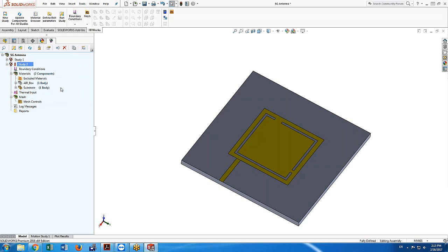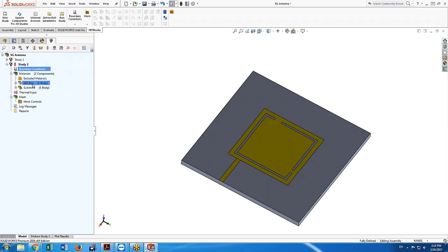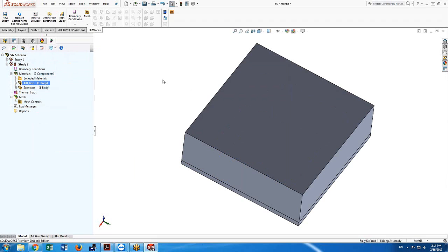That's how the feature geometry looks. So you get the boundary conditions, and the boundary conditions are really straightforward for antenna. Port is port. In this case, let me go ahead and show the air, because air is an important medium for electromagnetic analysis. As a matter of fact, that's how the wave propagates. Antenna really is a wave. Instead of propagating in a waveguide, it propagates in air, in free space.